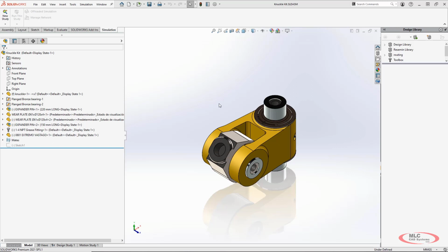Then also that you're going to have small deformations. You're not applying so much force that it permanently deforms. And the other assumption is that the forces are applied slowly over time and you aren't doing dynamic effects. There are other modules within SOLIDWORKS to do that, but within Simulation Standard, those are the assumptions we have for our linear static studies.